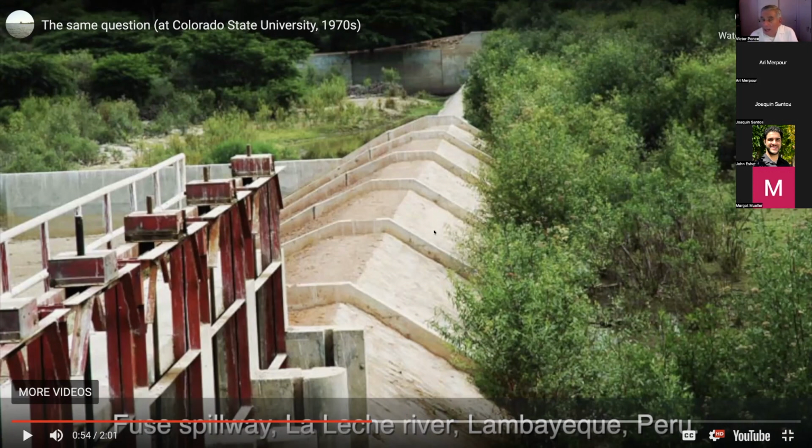It so happens that since this watershed is not well behaved in terms of flood predictability, the designers in this place have put a fused spillway in here. In other words, the flood would go right behind the trees over here, but if the level of the flood gets above this stage, it'll go over the spillway and it will breach, it will break within an hour.